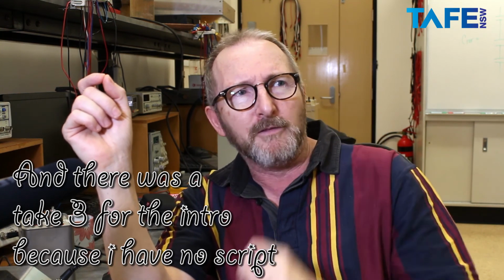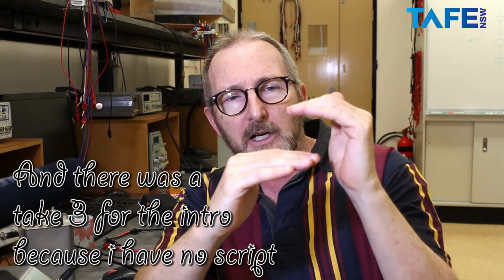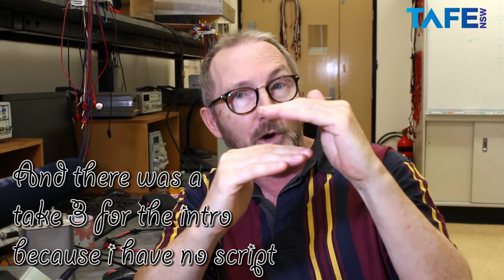But what about the half? Well, as the two plates are charging and we've got the holes developing in the positive plate and the electrons developing in the negative plate, that resultant voltage, the potential difference between those two plates, is bucking the charging voltage for the capacitor. And because the charging voltage is being opposed, we've got this slowing down of the charging process as we get more potential difference across the plates. So the further we get into the charging process, the slower the charging process is.